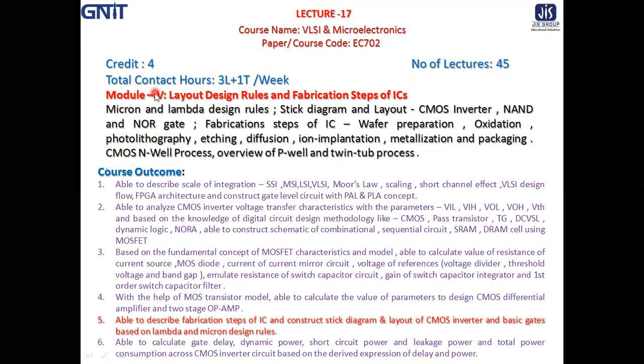Now we are in module 4, that is layout, design rules and fabrication steps of the ICs. In module 4 we will be studying the following topics. First is the micron and the lambda design rules, then stick diagram and layout of the CMOS inverter, NAND and NOR gate, fabrication steps of the ICs such as wafer preparation, oxidation, photolithography, etching, diffusion, ion implantation, metallization and packaging, then CMOS envelope process, and overview of the P-well and the twin tub process.